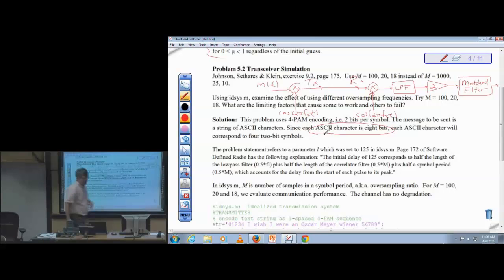Now the problem is going to come in, as we'll see in just a minute. There is a value of capital M, which is our oversampling factor, and it's put in here in a way that it is both the oversampling factor as an integer and also a sampling frequency. So it has 2 roles to play for the same value. It's a bit strange. In this problem, we've got 2 issues: one is aliasing, and the second is the gain of 2.